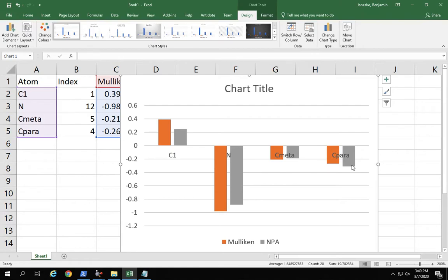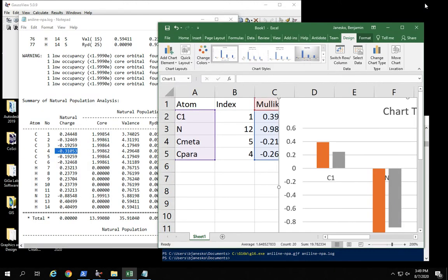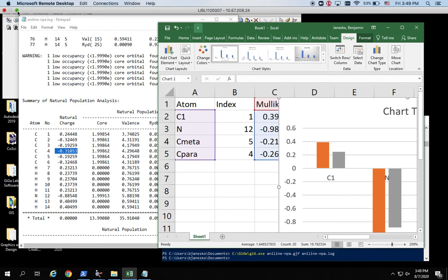So with that, I've shown you how to compute orbitals and look at them in real space. I've shown you how to compute densities and electrostatic potentials. I've shown you 2 different ways to compute atomic partial charges. And we've learned a lot about working from the command line, which is going to be the most reliable way to get GaussView working. So with that, we will close this video.